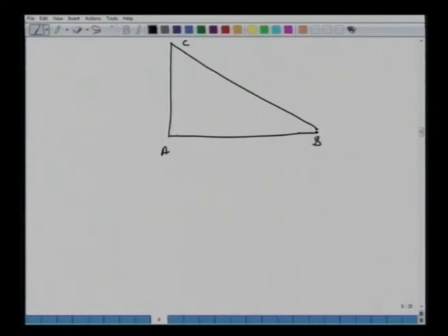So here if we fix this R and P and connect this S, this can go either way. To locate this F, find this tie line which you extend to give del min. All right, if the tie lines are downward, then find that tie line which you extend in this direction. This will give you del min this way.